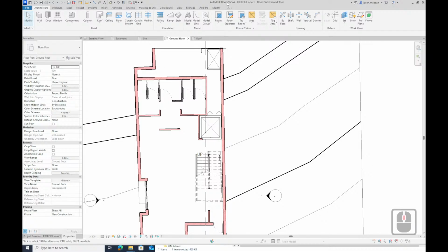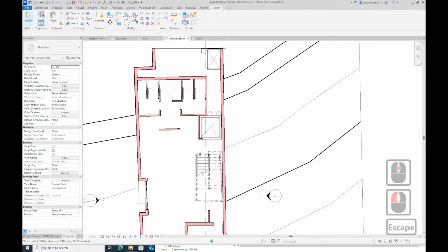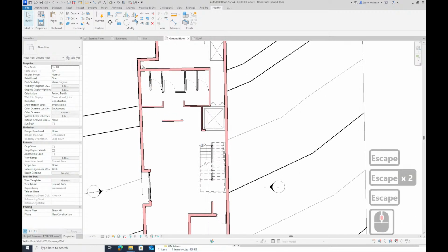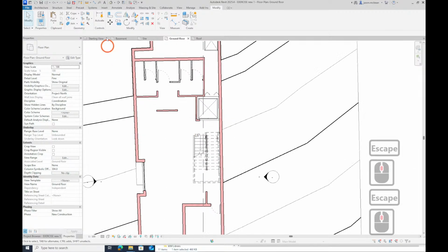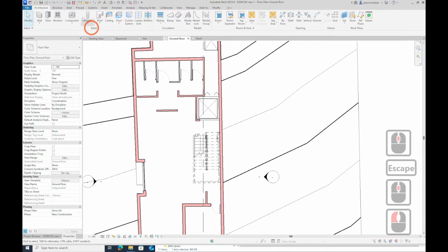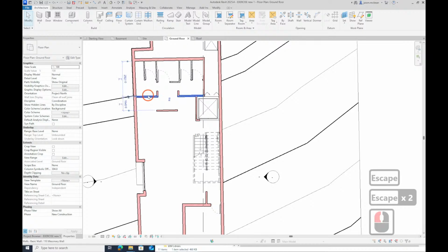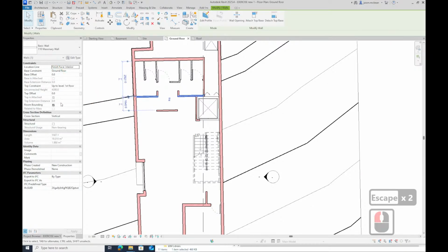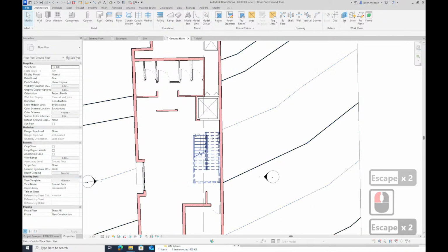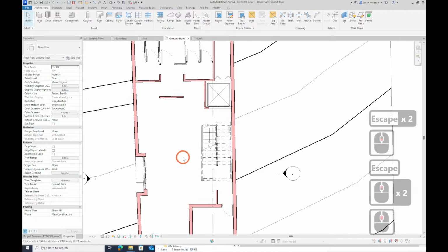If you go to modify, I actually use fold regions to measure my areas. If you select a fold region, let me show you this. If you go to architecture, fold region, you can use this just to show, or you can make an area plan and do it that way. But the problem now is you're going to make sure rooms are room binding or not room binding. Then you're going to room separator tags. Oh my word, you'll be here for 6 months.